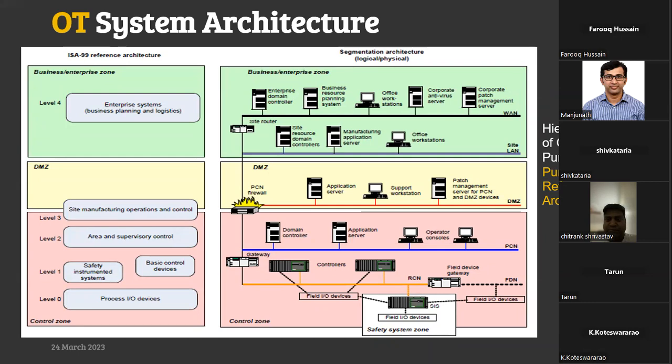And recently, from the past 2 to 3 years, I have seen end users requesting a separate firewall for Modbus. Why do they need it? Because the attacks were happening by using the unused registers of the Modbus, right? So that is why there are some industrial firewalls available nowadays where you can block those registers which are not used. Thereby you can mitigate the risk.